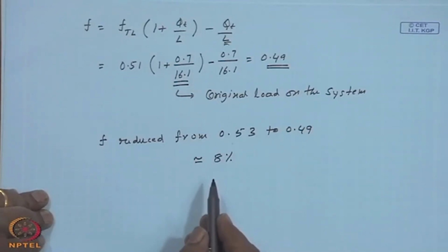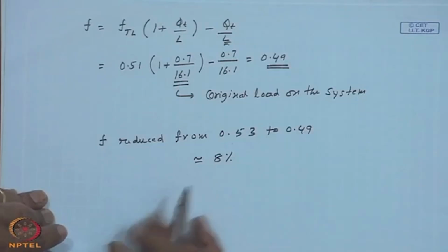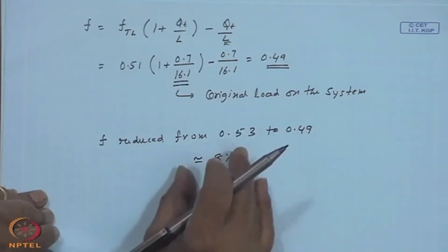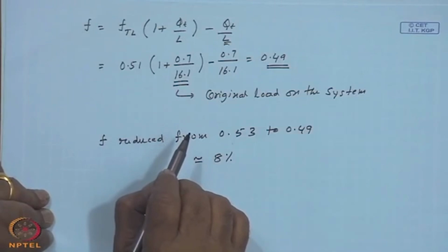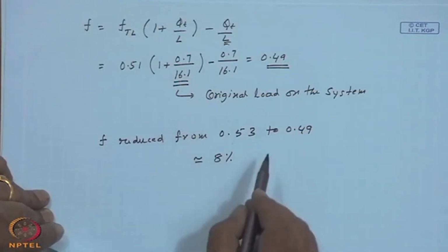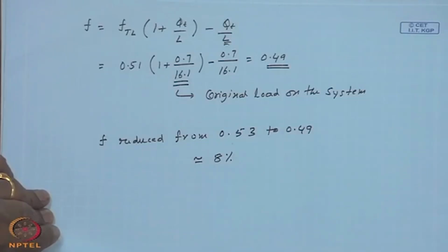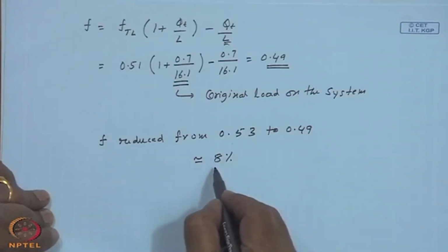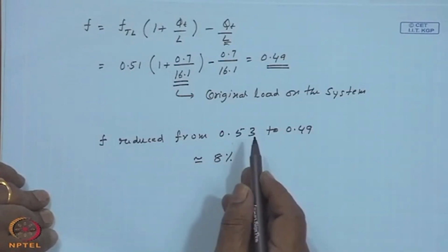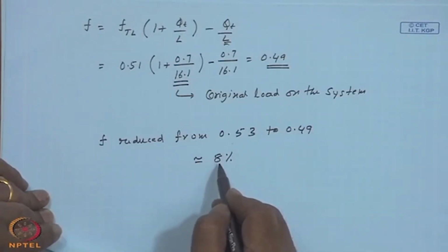So, tank losses will reduce the solar load fraction by about 8%, but that can depend significantly upon the minimum temperature at which energy delivery is needed. In the case of the F chart, it is a single unit, so the correlation takes care of the losses, etc. In the case of the phi bar F chart, if it is 60, and if you have got 80, it would have been a much higher number than 8%.